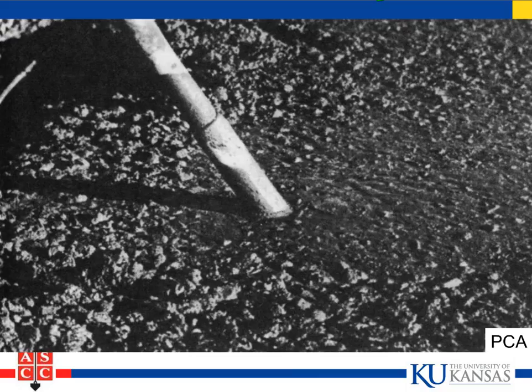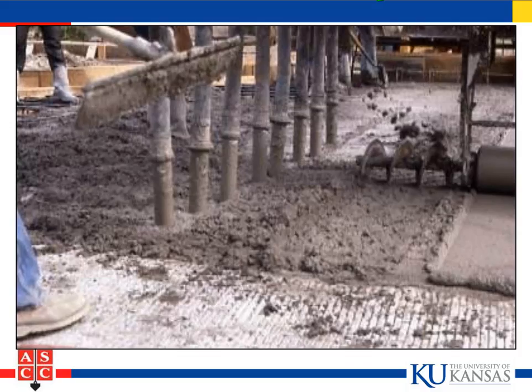So how do we reduce the potential for settlement cracking? One is to get good consolidation. This is a procedure that's used in Kansas very effectively on bridge decks. It uses vertically mounted internal gang vibrators on 1 foot centers before the finishing, before the roller screed.